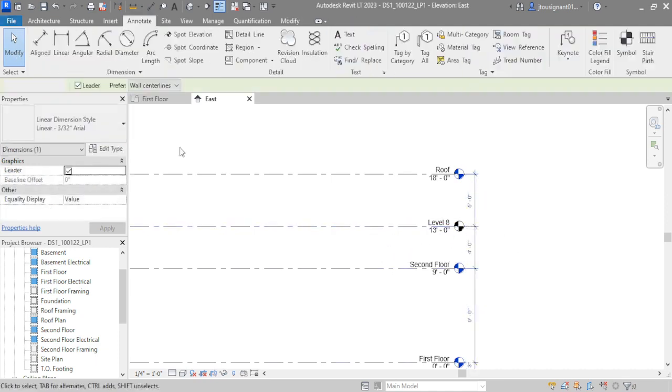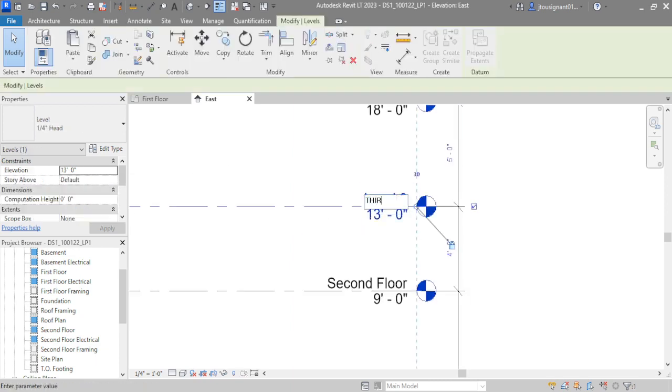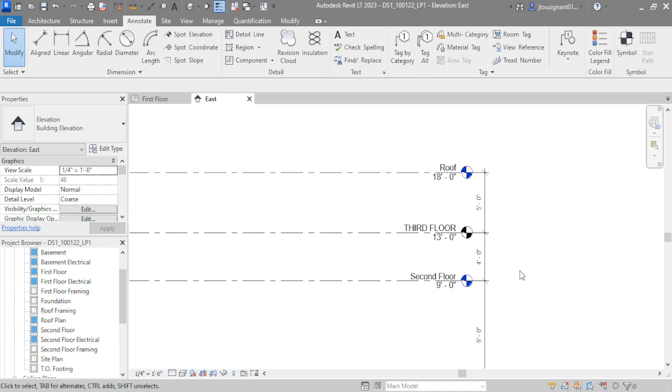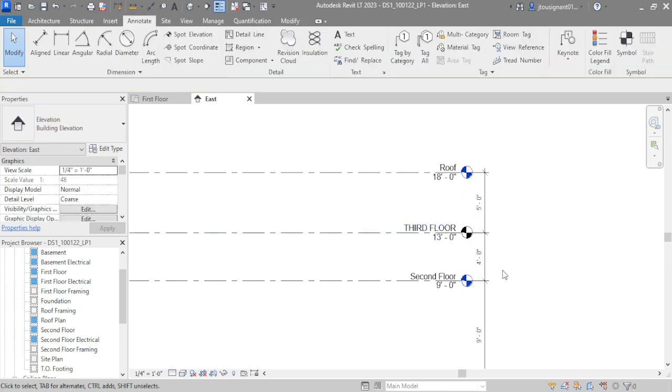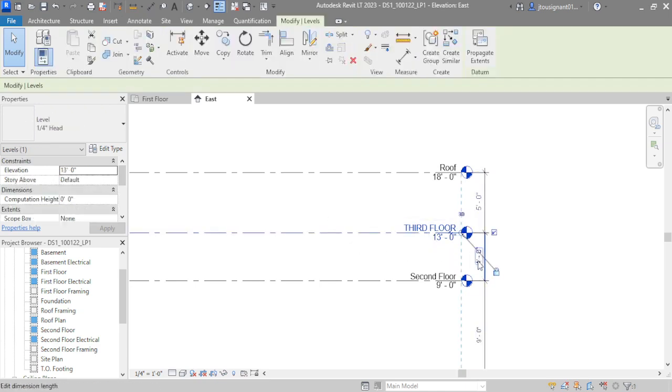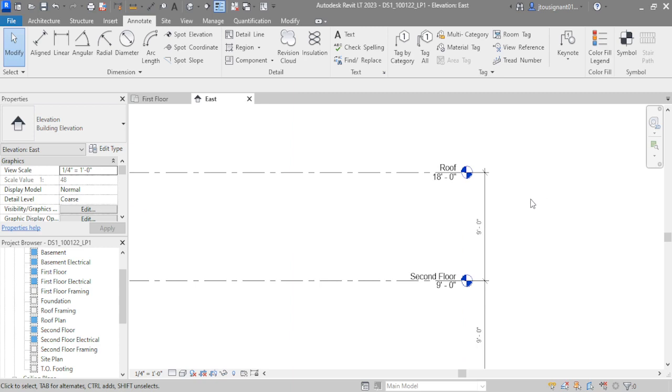I don't have to have that pressure of thinking, oh my gosh, I just copied this up and made my third floor be 4 foot above the second floor. That's a catastrophe. There's always a way in Revit to either click on the item and change its properties that are inherently built into it, or select items and refer to temporary or standard dimensions and tell the items to adjust themselves later. So that's a lot of pressure you could take yourself off in Revit, is knowing that as you're drawing, everything that you're doing can be very, very easily changed.